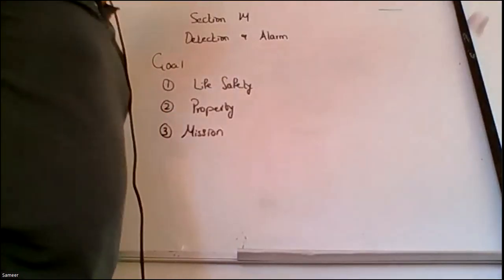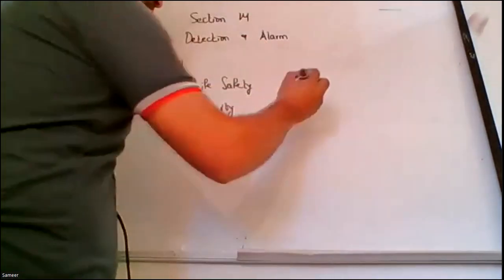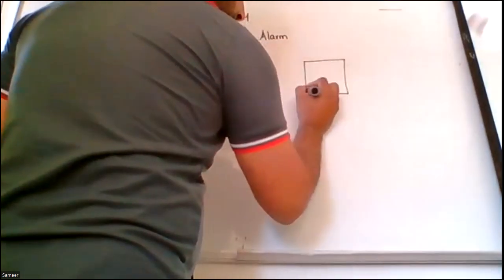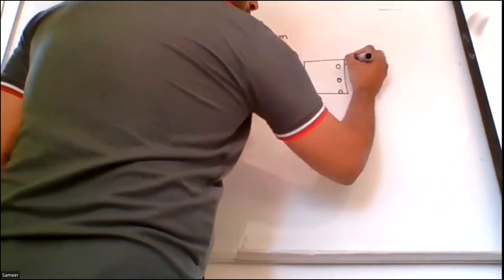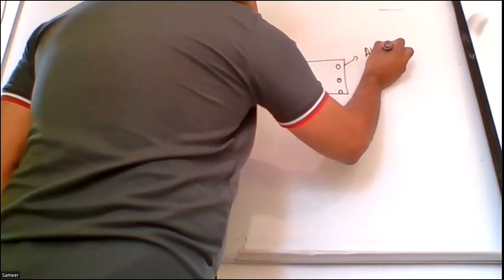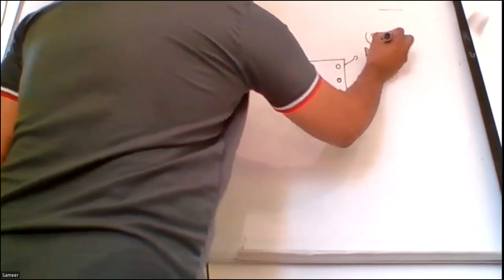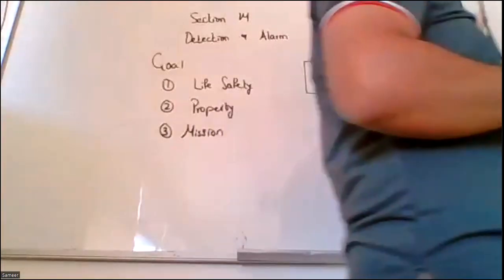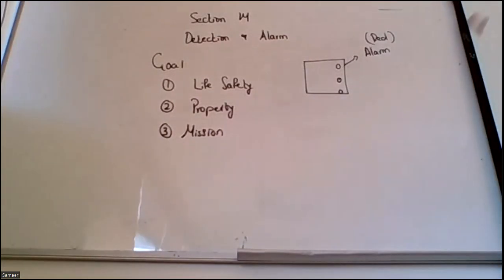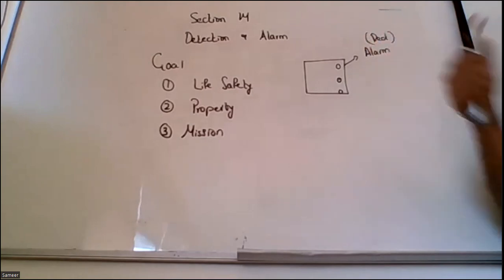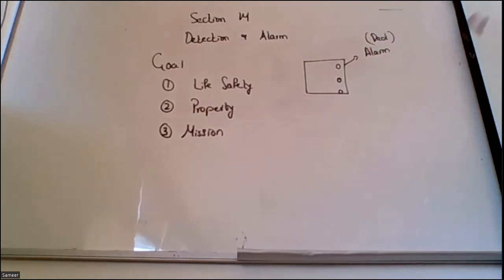In the fire alarm system, we usually have signals that are available with us. Three types of signals are there. The first signal is usually an alarm with a red identification. Usually, a red light blinks in the fire alarm control panel. When this light blinks, it indicates that a hazardous situation has occurred. Meaning, any of my initiating devices has operated, whether my smoke detectors, my manual break glass, or sprinklers have operated. So a red indication will be there, indicating a threat is there.